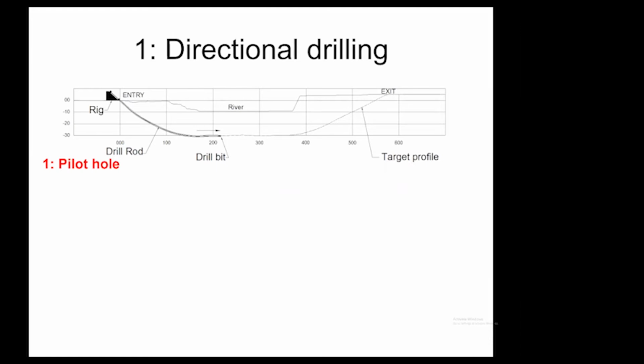The idea is that the contractor has a special machine, a drilling rig, and that machine first of all angles down from the surface, and the drill string, as they add more and more drill rods, is then steered using a bit that can be steered so that it goes horizontally under the obstruction. It could be a river, a highway, a railway, maybe an environmentally sensitive area.